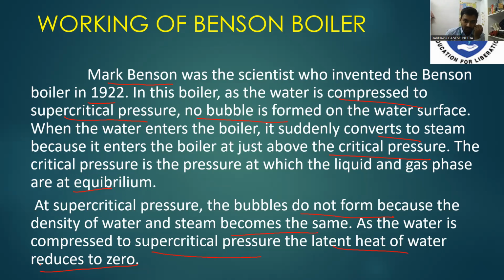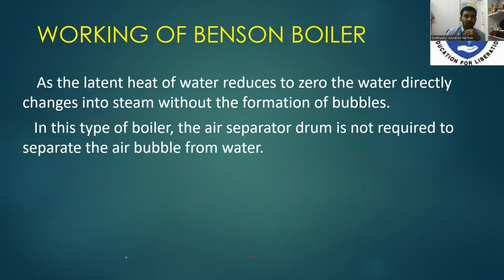The latent heat of the water reduces to zero, so the water directly changes into steam. In this type of boiler, a separator drum is not required to separate the bubbles from the water, because as the latent heat of water reduces to zero, the water directly changes into steam without the formation of bubbles.